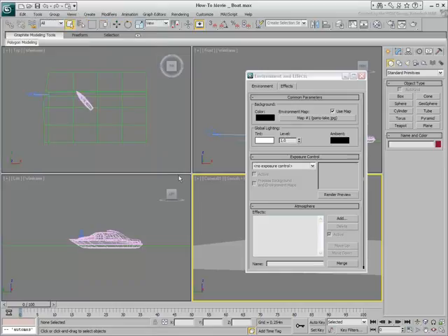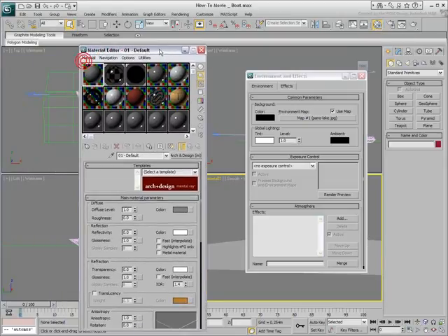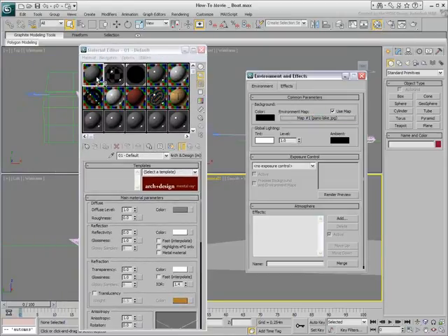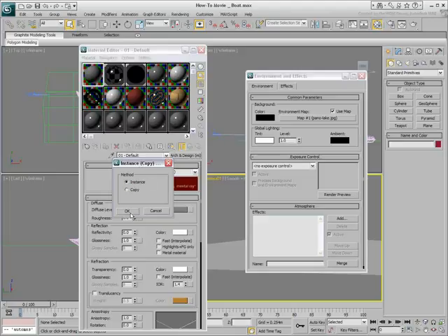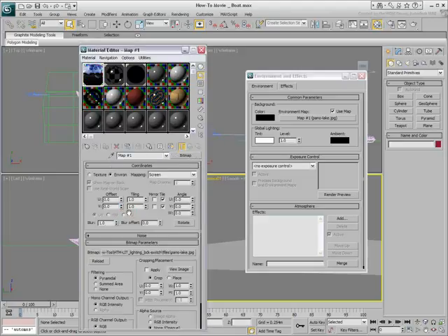A panorama background needs to be mapped differently than a single still picture. This is done by instancing the background into the material editor and changing some of its values. First, ensure that Use Real World Scale is off. You may need to temporarily switch to texture mode when doing so.